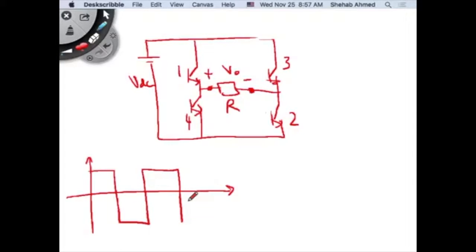And you cannot use a regular boost converter because we saw the limit on boosting ratio is what? 4 times, for example. So from 12, you cannot boost to 180 volts. No way. So what's the solution? The solution is always a transformer. AC, but transformers do not allow you to translate DC voltages. They only allow you to translate AC voltages, right? The other solution is you can use 2 boost converters in series,